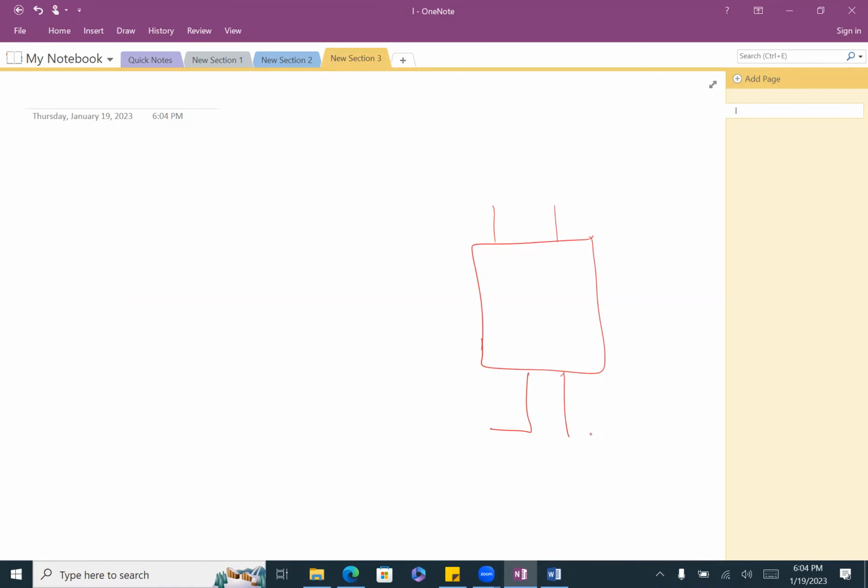That's the sum of 0, that's A of 0, B of 0, and that's C_i minus 1. Now, initially C_i minus 1 is 0, right? Because we don't have carry. And how do you give 0 in digital design? You just ground it. That's a ground, and that will give you 0 here.